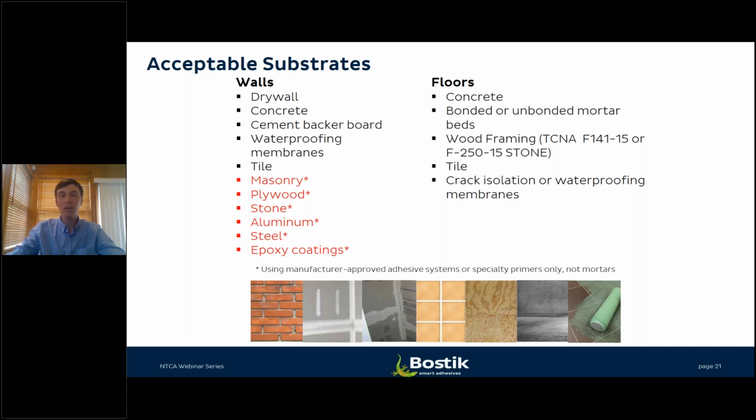For floor applications, the approved methods are concrete substrates, bonded or unbonded mortar beds. And then you'll find a few different methods per the Tile Council of North America handbook to go over top of wood framing, which would be the TCNA method F141-15 or F250-15 for stone. You'll find applications over top of existing tiles as well for floors, and then crack isolation and waterproofing membranes as well, although there may be different limitations depending on the type of membrane that's been selected or specified.